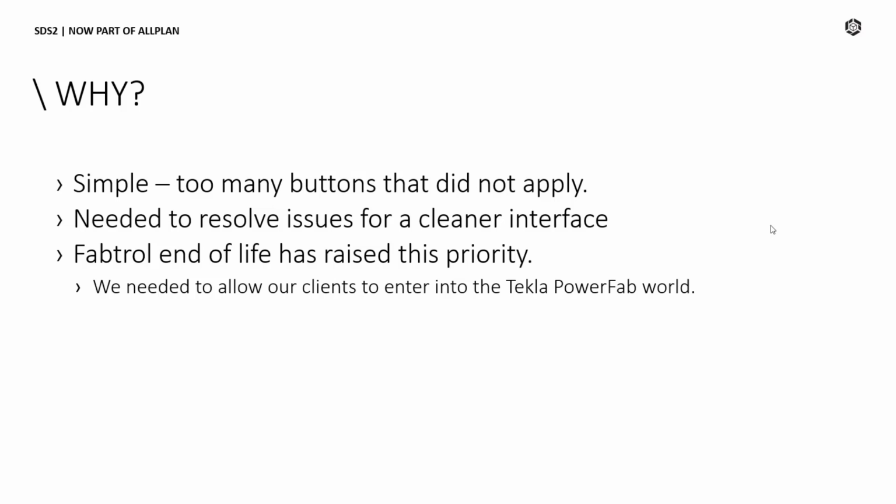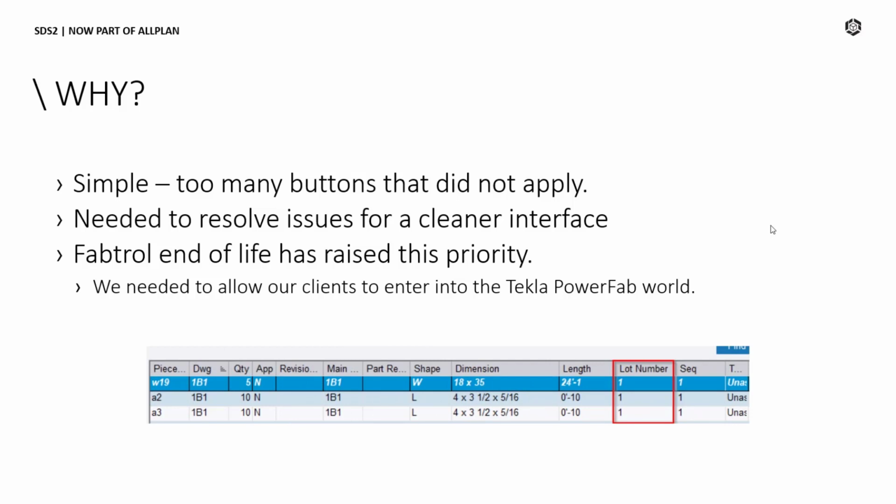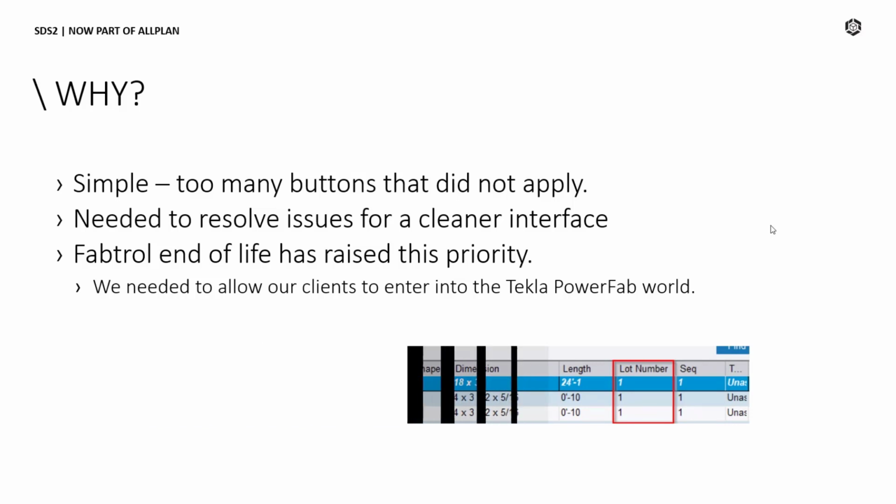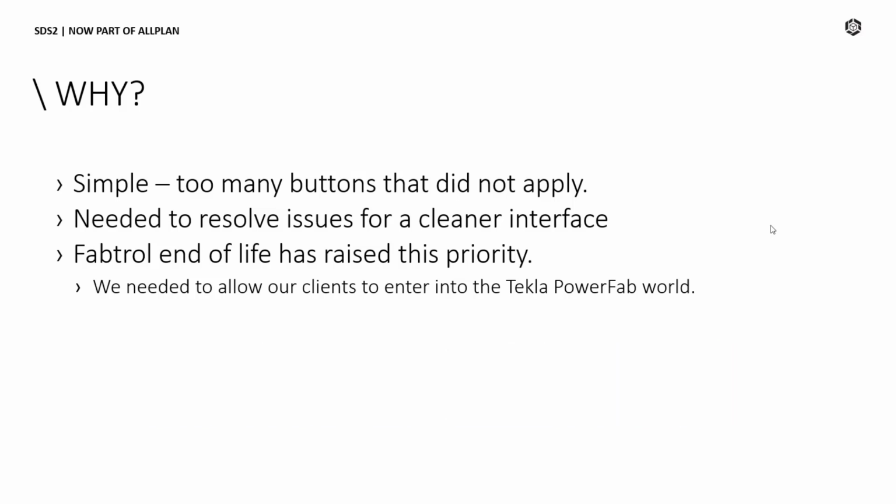We needed a dedicated export and import for Tekla PowerFab. Some of the information in the export would cause issues in Tekla PowerFab. For example, zones would override lot names on import, or details would cause an issue when the detail and the details sheet name matched. We'll come back to this topic in the presentation.